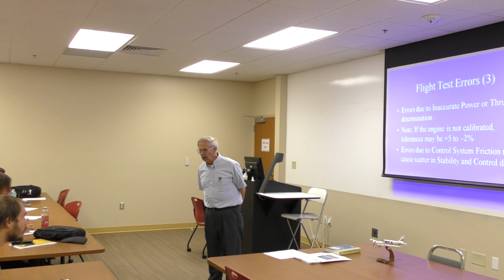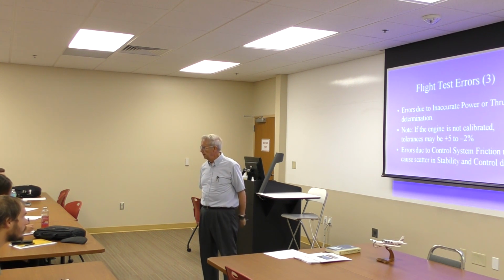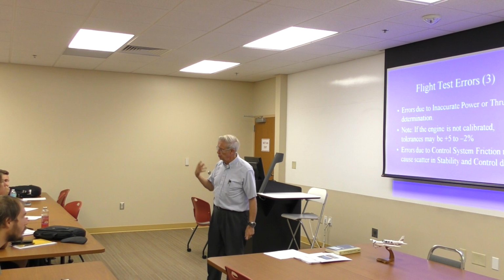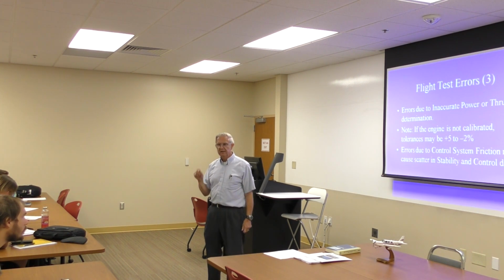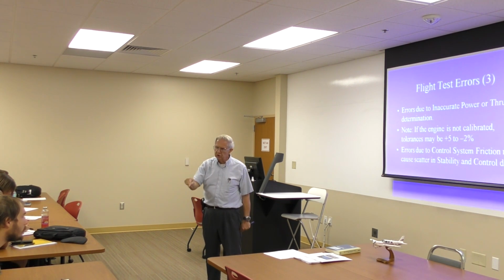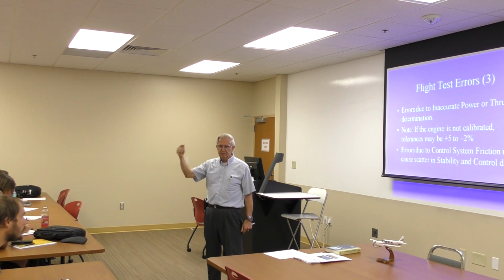But the FAA allows the manufacturer of engines to have plus 5% when they do their static run with the engine; it can be 260 horsepower plus 5%, or 260 horsepower minus 2%. Well, that gives you a 7% possibility, and what the FAA will assume if you don't have a calibrated engine is they'll say, okay, you don't have a calibrated engine, so we're going to assume that the engine that you tested was 260 plus 5%, and that all of those out there in the field